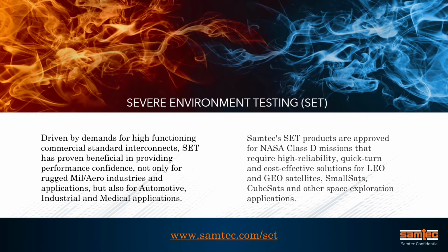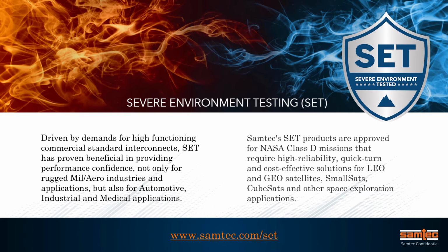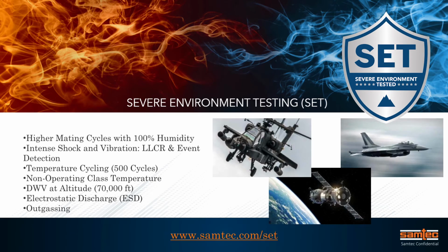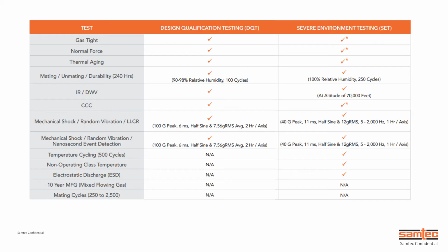Samtec has implemented a severe environment test. This is driven mostly by military and aerospace, medical, and other rugged applications. Samtec takes our existing qualification report and pushes it to the limits with higher mating cycles at 100% humidity, intense shock and vibration, higher temperature cycles, altitude testing at 70,000 feet, and ESD electrostatic discharge testing, as well as outgassing.